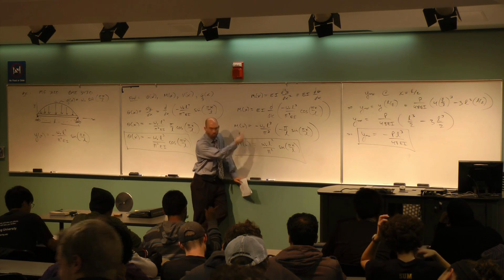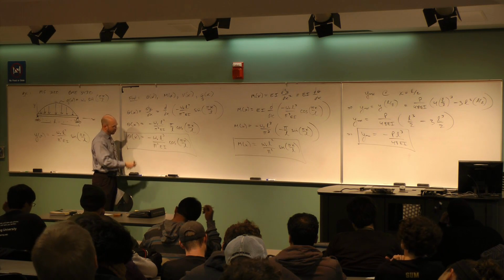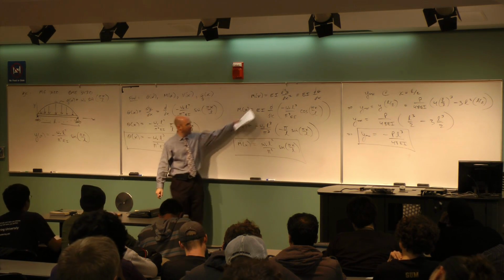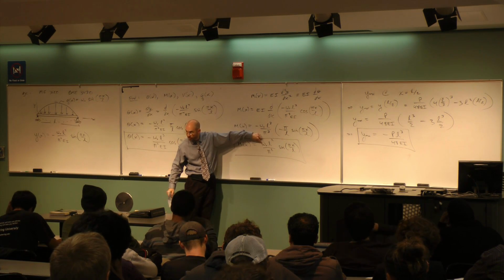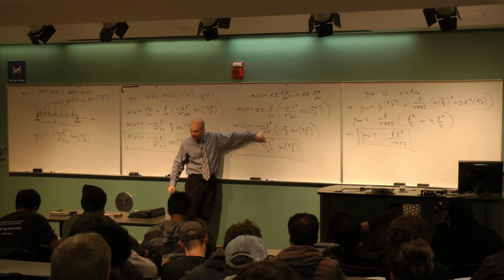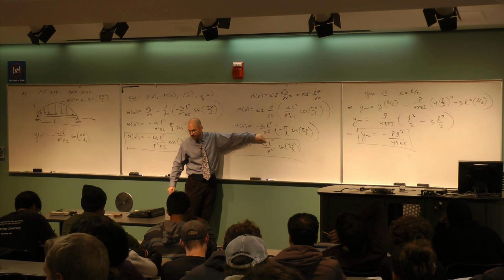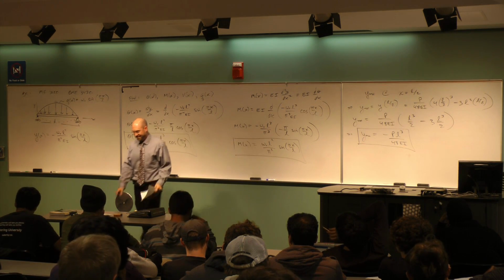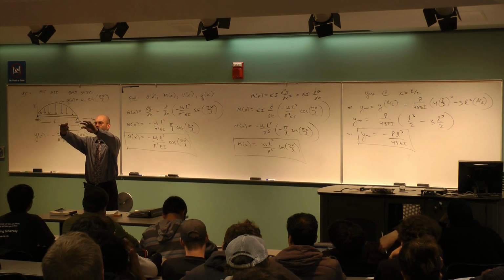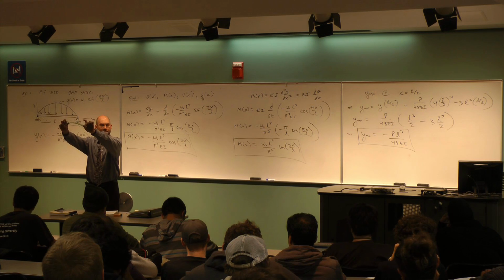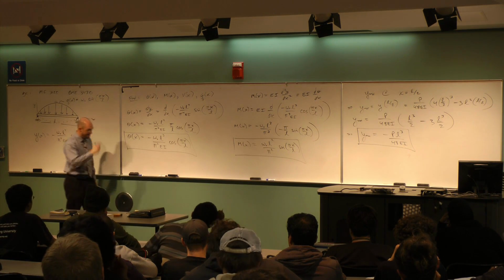The EI went away, okay? So going directly from here to that can get a little confusing because the EI goes away when you add that second derivative, okay? But this is pounds per inch times inches squared is pounds times inches. If you had physics, right, moment is what your physics teacher probably called torque. It's force times distance, right? So pounds per inch times inches squared is force times distance, pounds times inches.